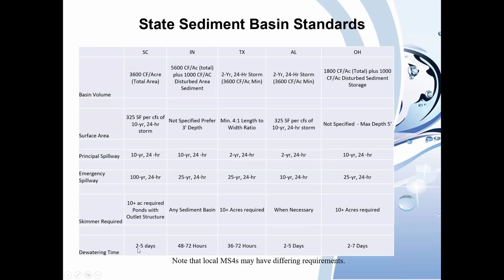And dewatering times, again, vary. 2 to 5 days is most common. Indiana's 48 to 72 hours. Texas is 36 to 72 hours. Alabama, again, 2 to 5. Ohio does allow 2 to 7, but we typically recommend trying to stay in that 3-day target time frame.